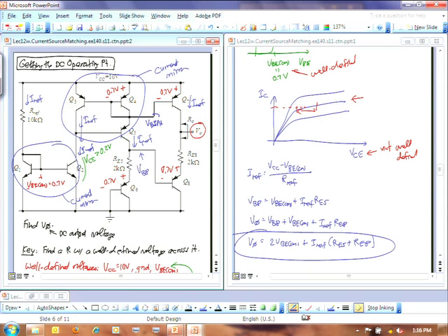Maybe you put the 0.7 volts in from the beginning, and the 10 and the 0.7 and the RF, and then you're calculating all that stuff. Don't do that. Right? Do it all symbolically first. End up with a compact symbolic solution, then plug the numbers in at that time. And maybe some of you are doing that. Maybe our homeworks are more calculation than you think. I think that's probably true too.